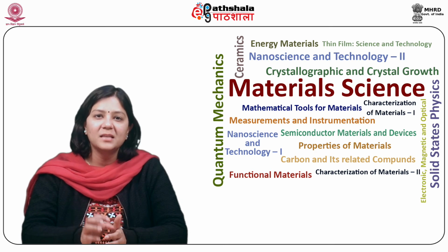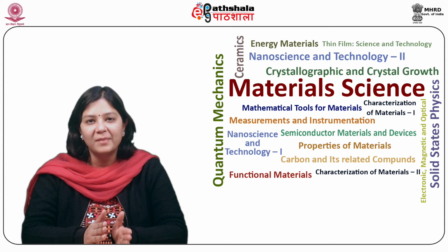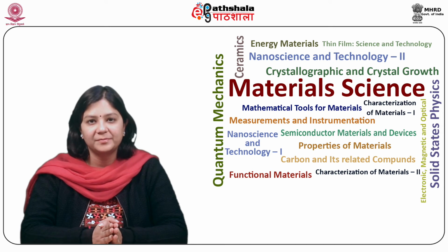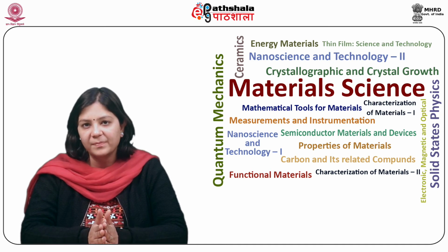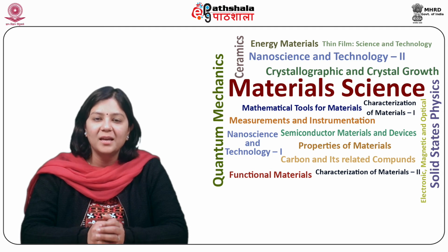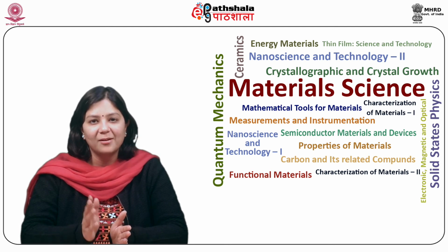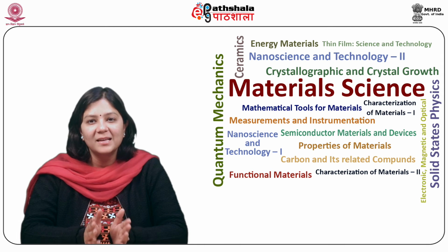These are the simplest type of exposure systems. In a contact system, the photomask actually touches the wafer and uniform light is exposed on it. In a proximity system, there is a small distance between the mask and the wafer. In both systems, the entire wafer is covered by the photomask and the pattern is created simultaneously on each. Both techniques require illumination of the wafer with uniform light intensity. The mask should be precisely aligned to the features present on the wafer.